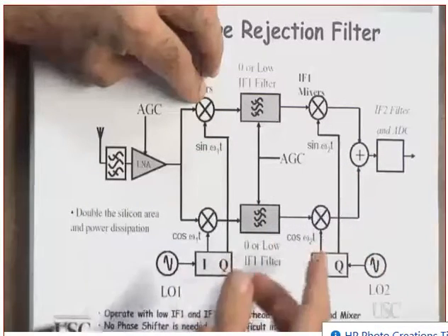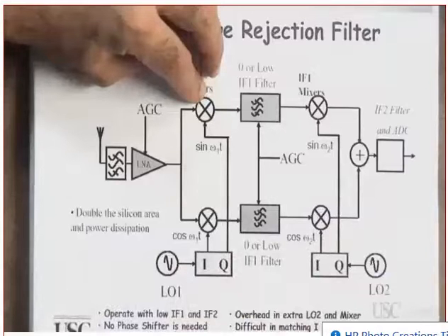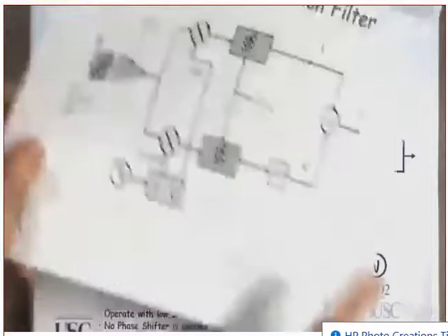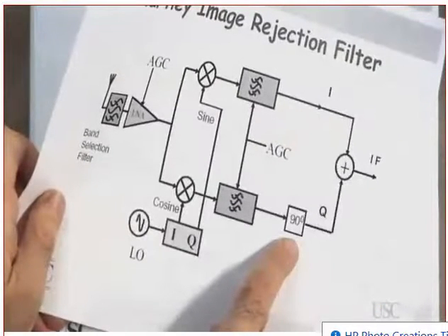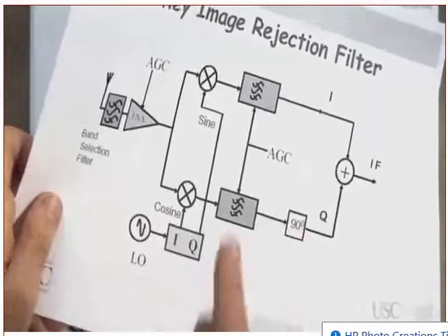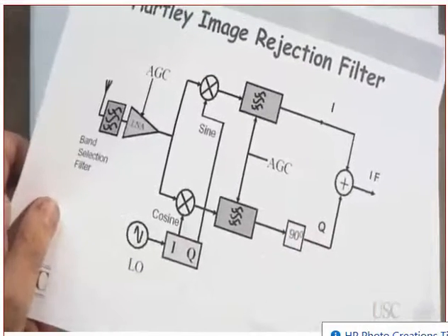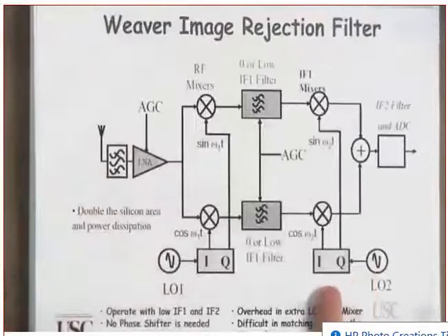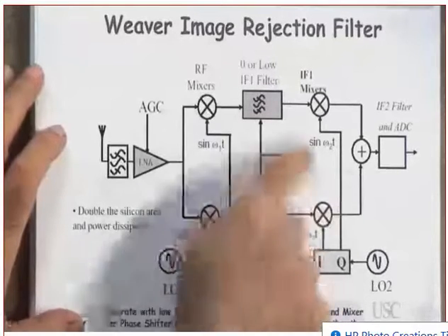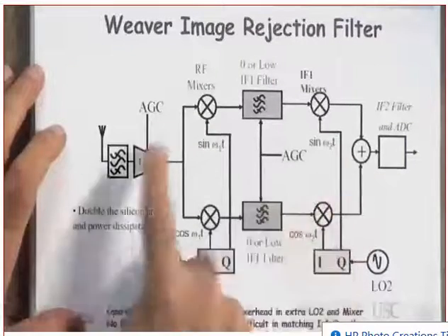Okay, but in doing so, what did I eliminate? I eliminated the need of using a 90-degree phase shifter. Did you get this or not? That I don't need this one. Remember, this one is hard to design because it's going to provide 90 degree over the band. There's in here nothing. I don't use that, but I'm going to use a couple of mixers, IQs.